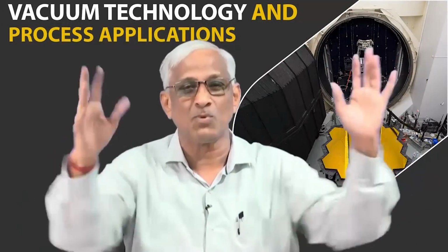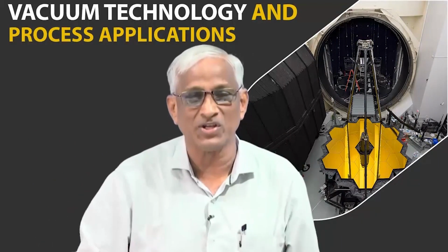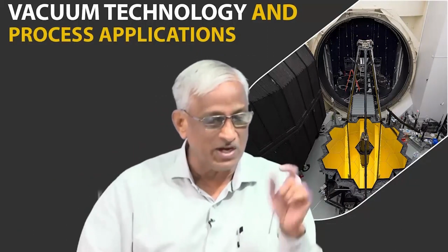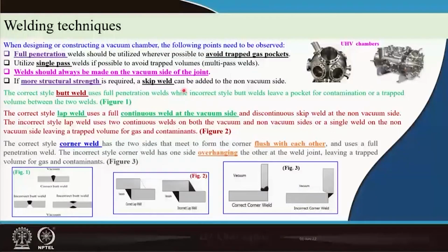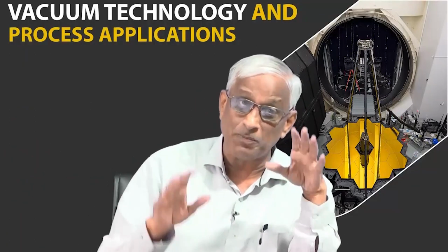Preferably the entire thing is a monolith, but that is not possible. Some pieces have to be joined, but that joining you should do from the vacuum side. So, welding should always be done from the vacuum side. Once we decide on the single pass and some skip welds for mechanical strength, and continuous inside welding and proper cleaning